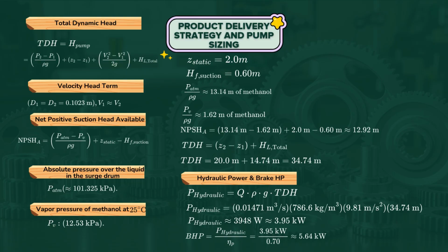The sealless design prevents the release of toxic methanol vapor into the environment, significantly enhancing reliability, uptime, and safety compliance, while MagDrive pumps may experience minor eddy current losses, potentially leading to slight efficiency reduction compared to sealed equivalents. The paramount requirement for zero leakage in methanol service makes the safety benefits outweigh the slight energy trade-off.